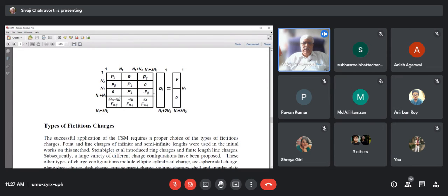So it is not a 100% full matrix, but still you can see there are only small segments of this matrix which are 0, the rest are all occupied. That means the rest of the coefficients are non-zero. So the charge simulation matrix for a single dielectric is fully occupied. But in multi-dielectric, it is not fully occupied, but on average, it is 70 to 80% occupied.